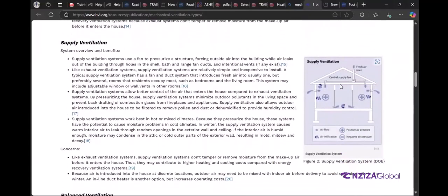So a mechanical ventilation supply system uses supply of outside air to the space. So the fans supply the air, you can see here is an air handling unit. Air from outside is forced through the central supply fan, transported through the ducts, and forced into the space.